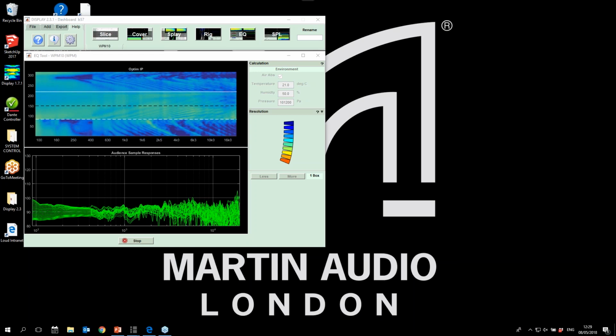And this optimization will give us a set of EQ filters which will be considered the optimized EQ curves, and they will be loaded into our icon amplifiers, which will determine how the array behaves within the parameters that we've told it to.